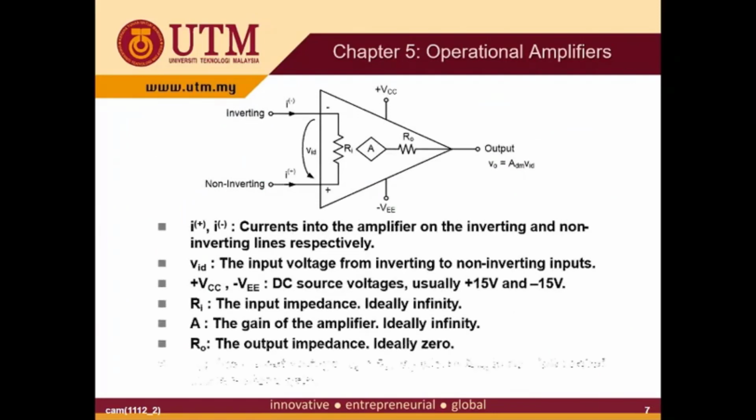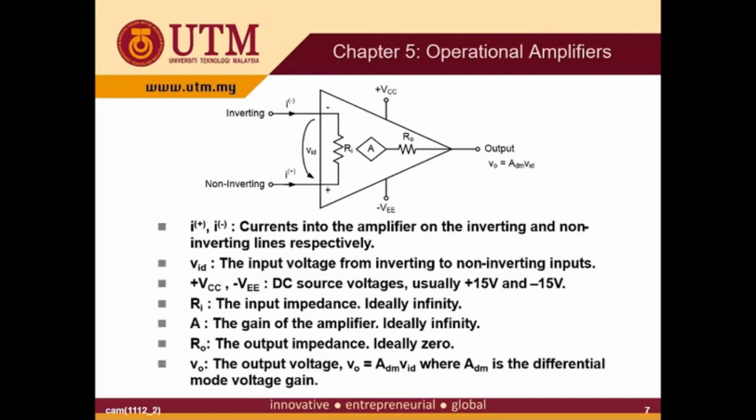As the op-amp is an amplifier, we can represent the op-amp using the general model of an amplifier, which we discussed in our previous chapters. For the general amplifier model, we have the Zi, input impedance, and the amplification effect is represented by a voltage dependent voltage source, A_VOC times Vin.